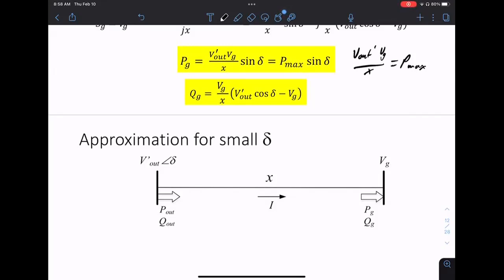Again, if you look at this equation and you think back to Tesla and Edison, when they're talking AC and DC. The reason to have AC is that the voltages are high, which means the losses along the lines are low. That's sort of the whole point. You want small current flowing on the line, so you have smaller loss. So if you look at this equation, the voltage is large, which means these are large numbers. To drive power flow, if these are large, you have small current, but that will mean that this angle is small.